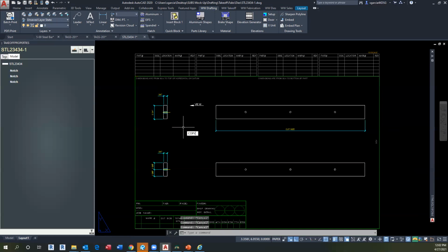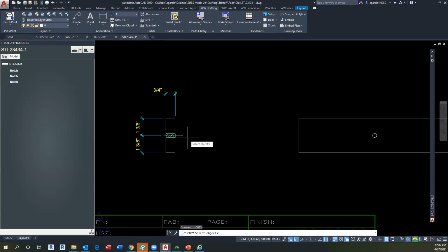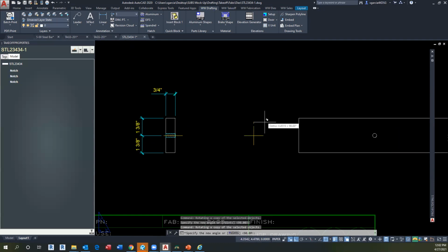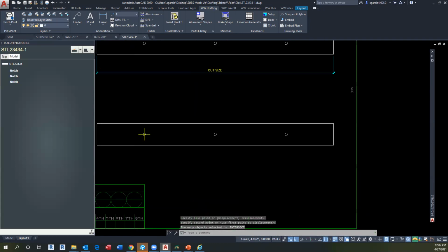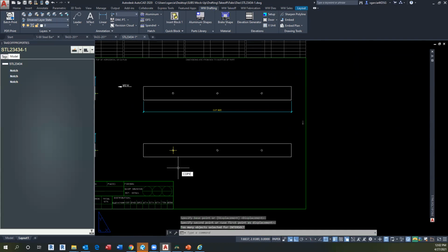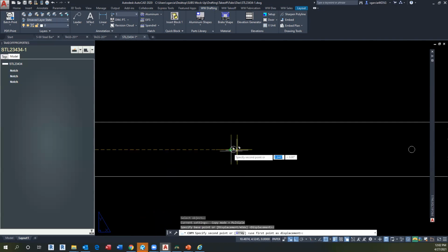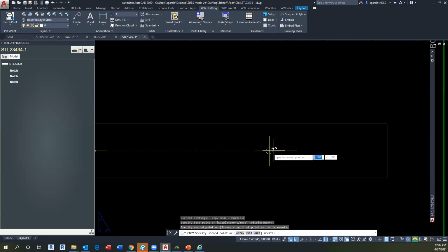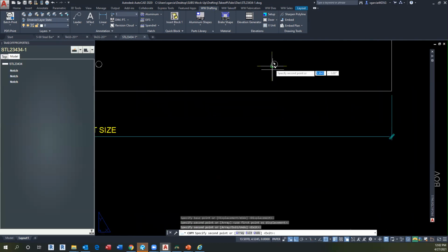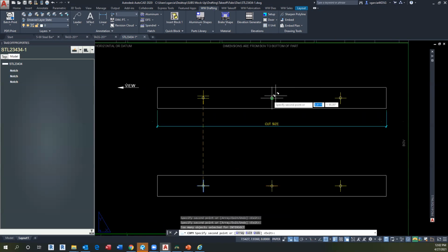But before we do that, I'm going to copy the center lines and move them into my little part here. If I use the CR command, CR, it's going to copy and then rotate at the same time. So I'm saving time there. So I copy here and I just place it into the center. So the only thing I need to do is just copy this one here in each single center hole in order to have a reference line. And there you go.